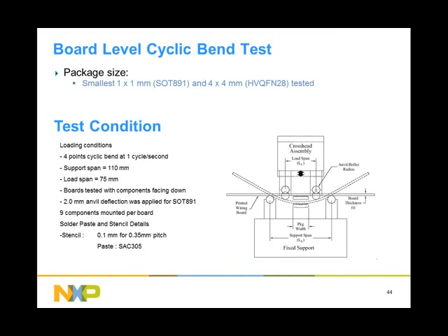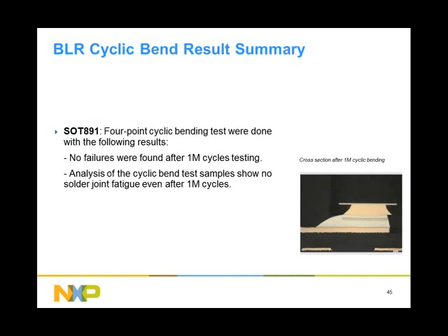We did this repeatedly over time, and we found that after a million cycles, no MicroPak, the SOT 891, was dislodged from the PCB. Not only were there no devices dislodged, we also did some X-ray analysis, and we discovered that there were also no solder joint fatigue problems with the devices after a million cycles.